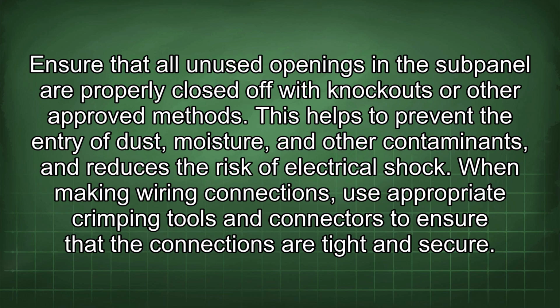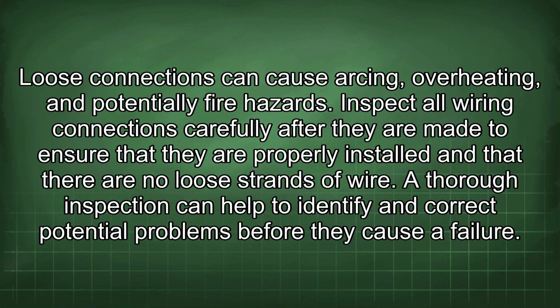When making wiring connections, use appropriate crimping tools and connectors to ensure that the connections are tight and secure. Loose connections can cause arcing, overheating, and potentially fire hazards.